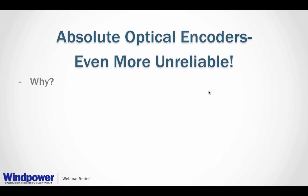Absolute optical encoders have these problems in spades, honestly, because they have multiple sensors, so that if any one sensor goes wrong, they have problems. Optical absolute encoders also are more precise, and so any slight flaw cannot be overlooked by the sensor. It'll often give you a position error. You often have plastic gears and couplings inside these encoders.